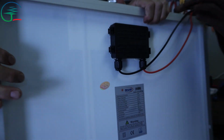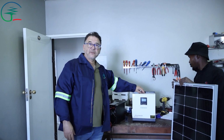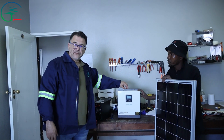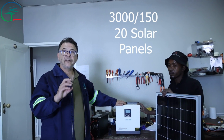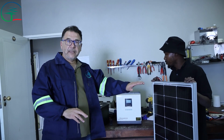You take your inverter's 3000 watts and divide it by 150, which gives you 20 panels. That's the maximum number of panels you can use on this inverter.